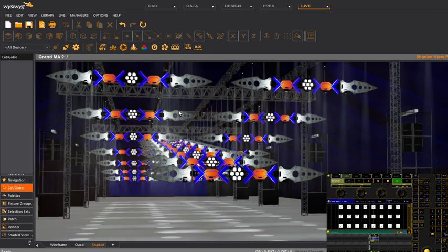Do you use any trick to emulate slow speed of motors? I just use fade times. Normally in real life, a motion hoist has a little bit of a curve, so it doesn't go from 0 to speed 100. It just slowly accelerates and decelerates. I think that's the right word. So it's not like a straight snap, because otherwise you put the pre-rig or the points where the hoist is attached to under a pretty big dynamic force, and you don't want that. So when it reaches the position, it slows down rather than just stopping immediately.